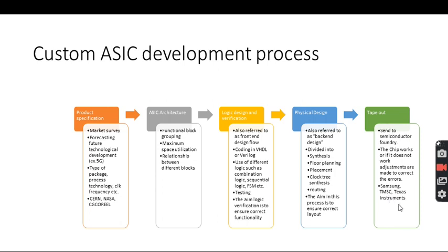Okay, so how the chip has to work, all those things, will come in the verification stage. Here the verification in software also will be there, and then after you create the IC, there also you will be verifying whether it is working properly or not. And if there is any problem, it will go back. Most probably before going to fabrication, everything will be dealt with, because this is a costly process. So most probably until the physical design itself, everything will be finalized.